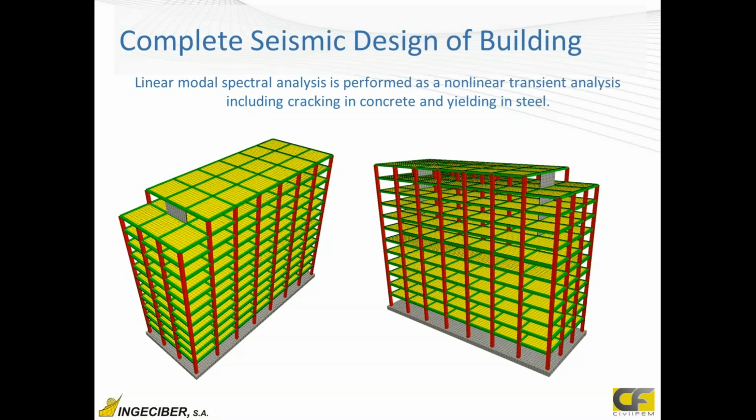the footing, the shear panels, the shear walls, and later we will go beyond, because with CivilFEM you can always go beyond and include a nonlinear and dynamic analysis. We can add nonlinear transient analysis, applying a displacement versus time table on the foundation.